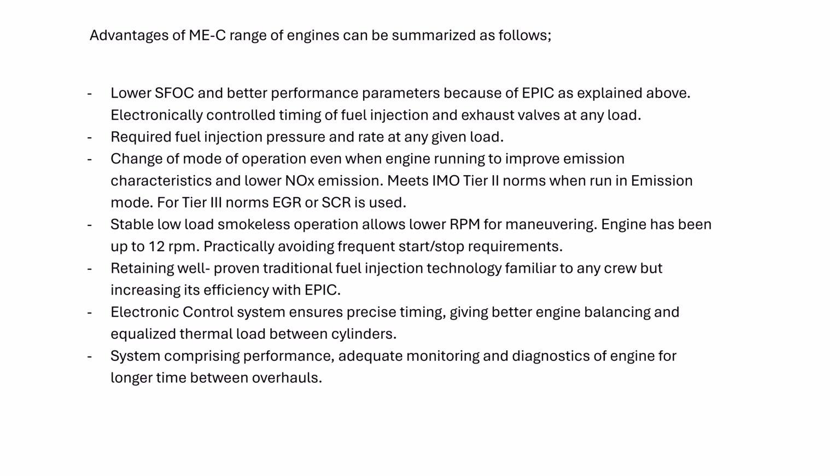We'll talk about electronic control in timing of fuel injection and the exhaust valve at very low load, also possible. Required fuel injection pressure and rate at any given load. Change of mode of operation even when the engine is running to improve emission characteristics and lower NOx emission. Meets Tier 2 norms when running in emission mode, also economy mode.